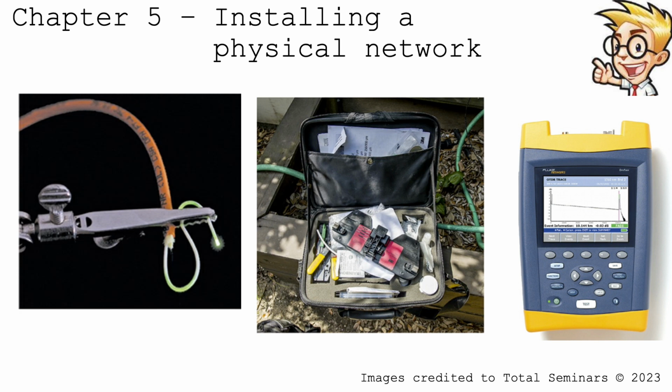Okay, installing fiber or dealing with fiber, because we just talked about copper. Yeah, fiber can have signal loss from light leakage. Here's an example of the light changing color. It's like white and then it's green. So you can see that there is signal loss here when it bends too much.